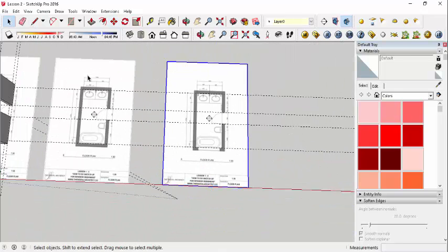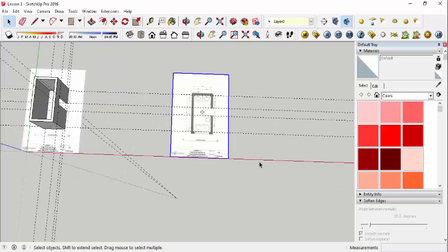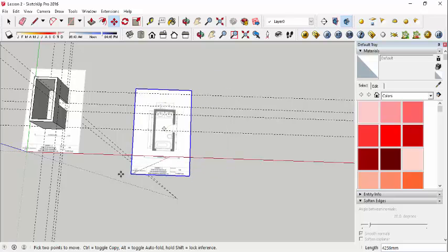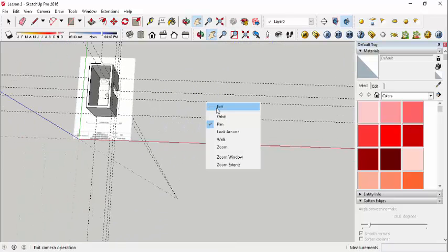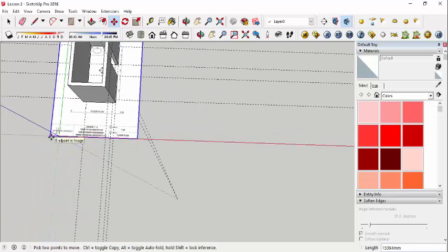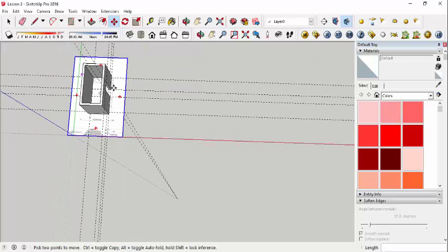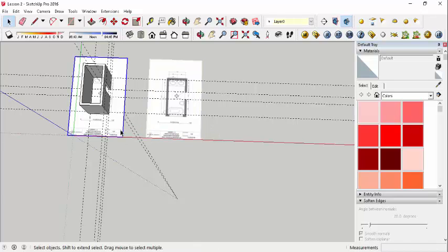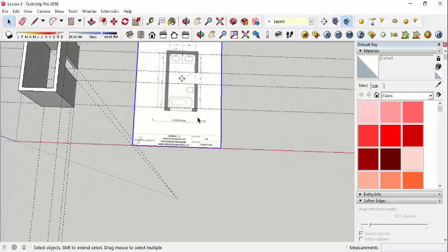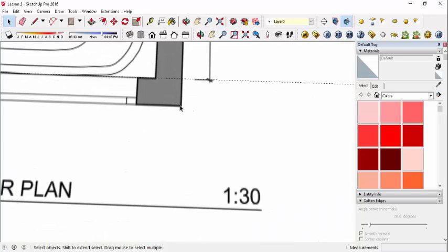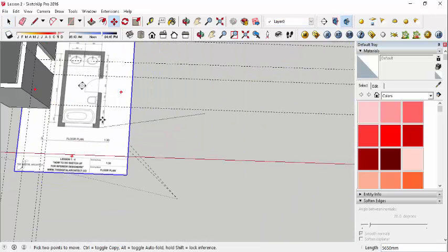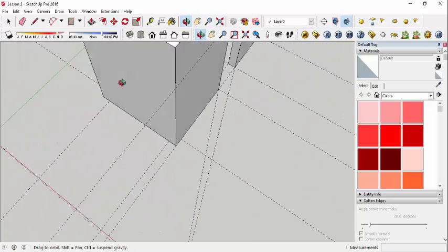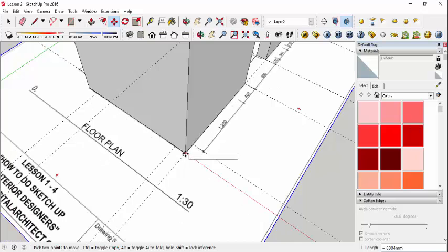Okay, so let's delete this, and then move this one right on top of the other floor plan, which is here. Okay, if you don't have the floor plans anymore, if you started without it, you can just delete. I'll delete this to show you how I will move it back to the same spot. Just get this corner as a reference point, click on M for move, click here, and then drag it to where your model is, and there, click it there.